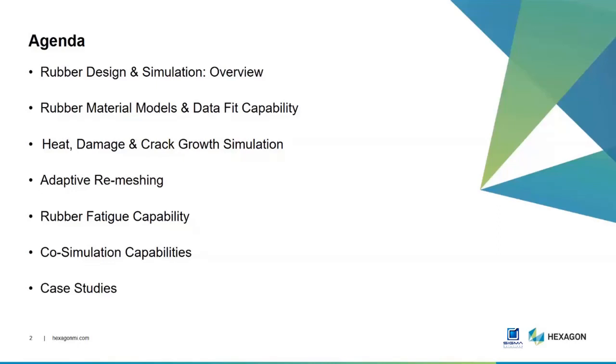With 2021.4, which is our latest release for MSC Marc, you also have the rubber fatigue capability. So you don't just get the stress and strain results; for mechanical fatigue, for certain applications, you can get the fatigue results as well. If you want to plot the damage or the life cycles that your component is going to see, you can plot that all within the Marc user interface.